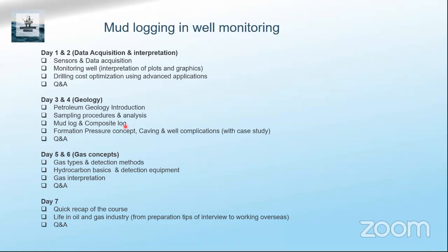The next part is, having studied all the samples and analyzed them, you have your data. Next is the mudlog and the creation of the mudlog and the composite log. The mudlog is nothing but a representation of all the formations, or rather the lithology of the well drilled, together with some other combined parameters, like the ROP, the rate of penetration, the gas information, with some comments, what the weight on bit was, and so on.